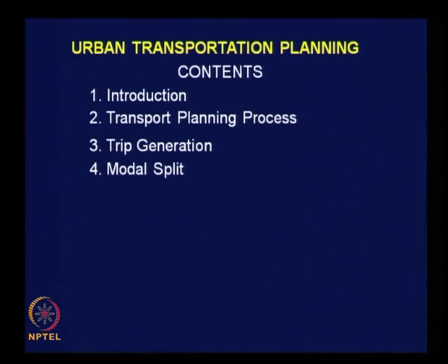Fourth, modal split. When we talk about trips, it is very important to know the mode used by the travelers, whether it is going to be a walk trip or bicycle trip or trip by transit or by car or motorized two-wheeler and so on. Unless this understanding is made clear, we will not be ultimately able to perceive the kind of travel intensity in terms of vehicle kilometers. How to analyze the mode choice process?